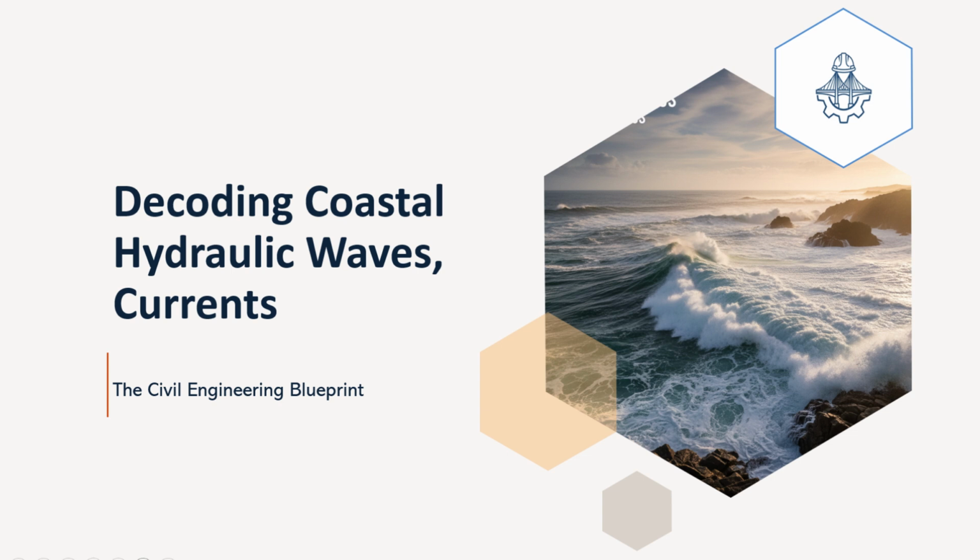So relatively small waves compared to the environment they're in. This seemingly simple assumption allows for a linearization of the governing fluid dynamics equations, making them analytically solvable, which is a huge advantage. Despite these simplifications, it provides incredibly useful first approximations for a vast array of coastal engineering problems, from calculating wave forces on piles to understanding basic shoaling patterns.